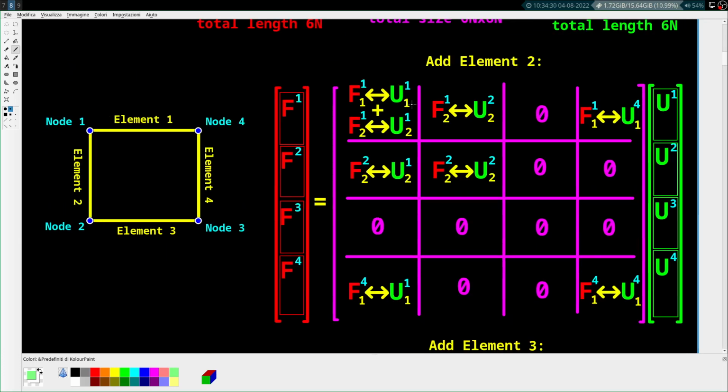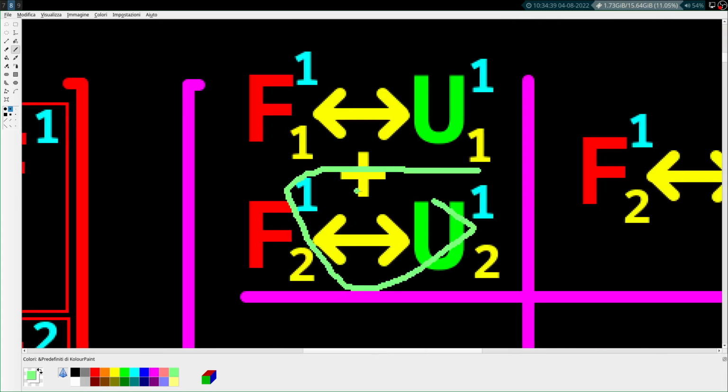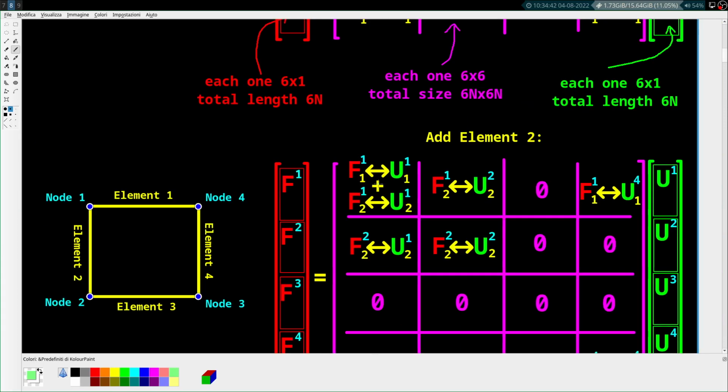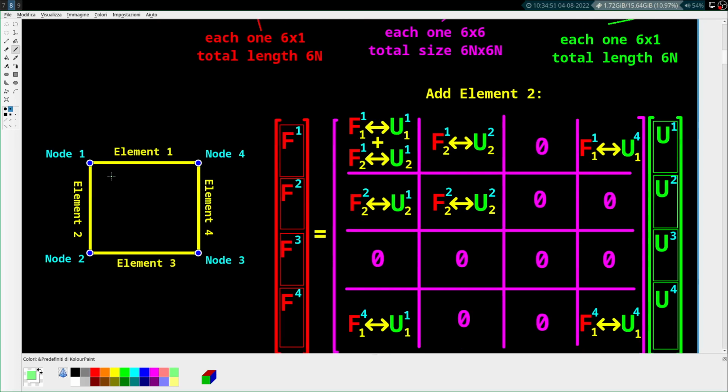So in that case, we're putting those 4 quadrants here, here, here, and here. And you'll see that for these ones, we just filled in the zeros, but here we actually added it together. So the stiffness basically has to be distributed. The force is distributed across both elements. If this element is made of reinforced titanium and this one's rubber, obviously more of the force is going to be invested in deforming this than this if they have to displace in the same degree of freedom. So you have to add them together, right?